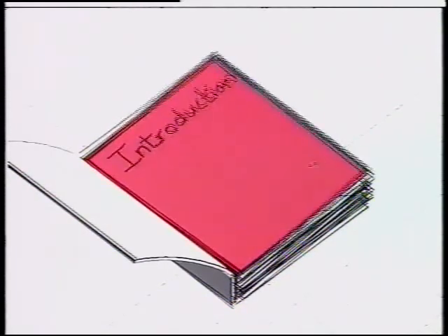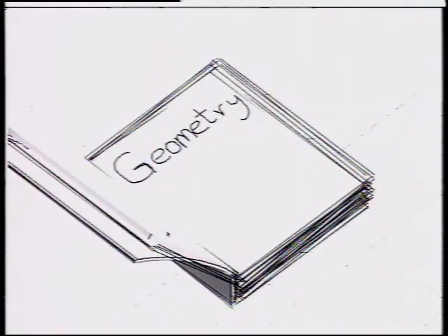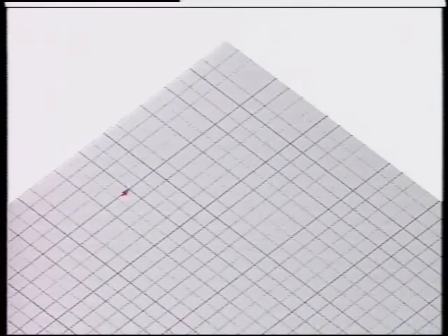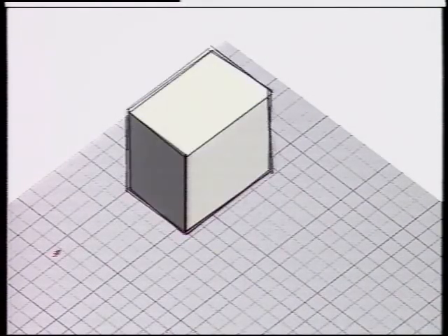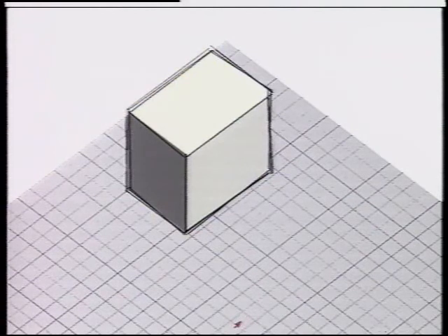The gestures used to create primitive 3D shapes are derived from their salient geometric features. In general, the gestures correspond to contour edges. However, for some shapes, the gestures are related to structural elements. For example, the user can create a cube by drawing 3 visible or hidden edges. Alternatively, the user can draw one edge and then 2 lines to indicate the cube's other dimensions. Notice that as shapes are created, the user's lines are constrained to the 3 principal axes.